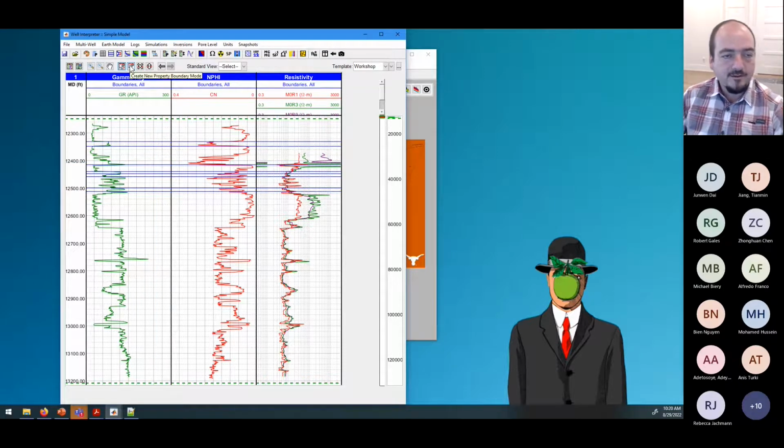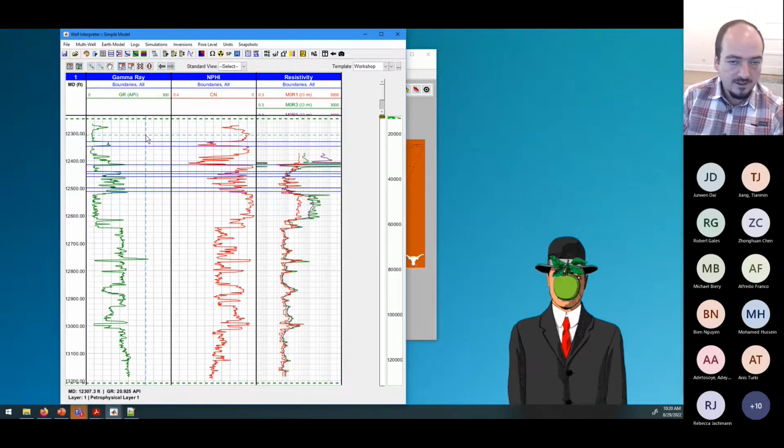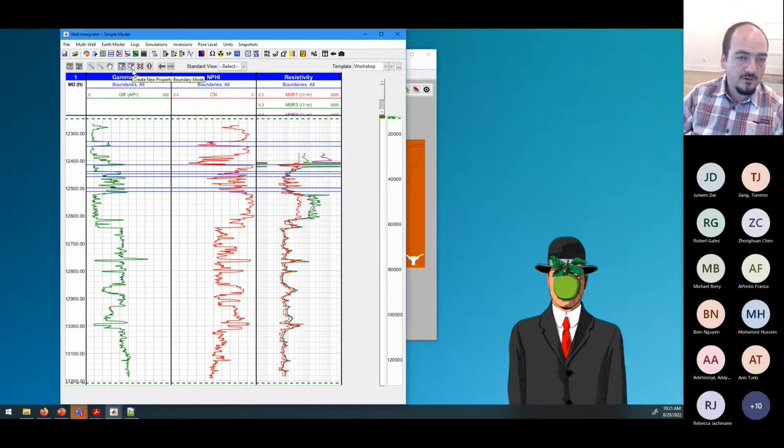The difference between property boundaries and petrophysical boundaries is that before we had this distinction, we only had petrophysical boundaries, but for some fluid simulations, fluid flow simulation requires higher resolution for the fluids than for the rocks, because fluids change more than the rocks. So we added another type of boundary, which we call property boundary, which probably should be called fluid boundary, but we call it property boundary. Across petrophysical boundaries, all properties can change, including physical properties: porosity, density, resistivity, fluid density, everything. However, across property boundaries, only the ones related to fluids can change. But we call them property boundaries for historical reasons.